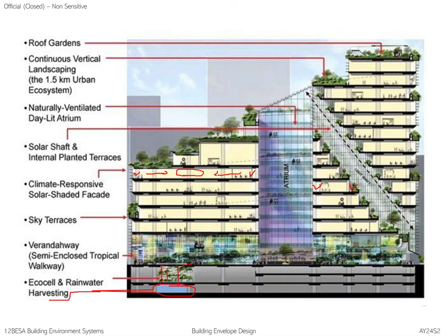If you look at this, it's actually like a giant shophouse whereby you have this veranda space, which is pretty consistent with, say, the void deck for HDBs. Because with that, if you allow the sun to enter the atrium, you heat it up, and the hot air will rise. So it creates this movement of air by drawing in the air from the veranda. That's why for the National Library you'll find that the atrium space is so generous, and it's always so windy.